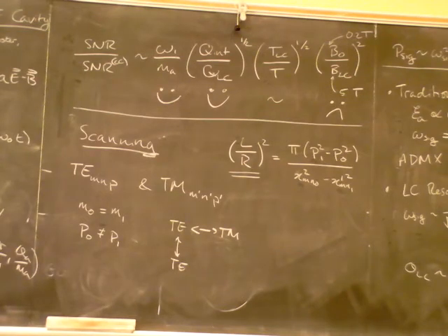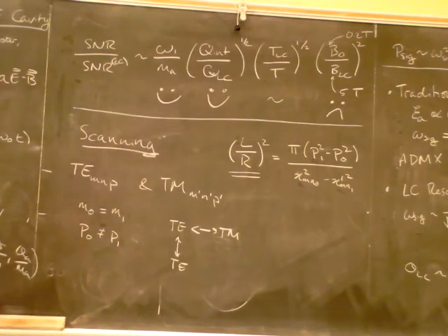So the length can be changed in two different ways that we have thought of so far. The first thing is just to exert pressure with piezoelectric actuators. And so if you use piezos, you can have tuning. So now I'm looking at changes in the frequency that go maybe up to a megahertz. This comes from the fact that over a meter-long cavity, piezoelectric actuators can maybe deform the cavity by about 1 millimeter. 1 millimeter in a meter-long gigahertz cavity is roughly a megahertz.